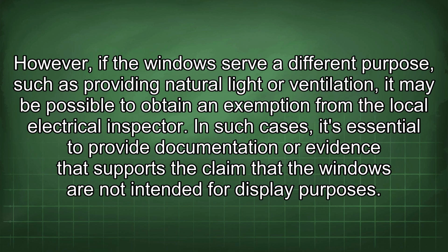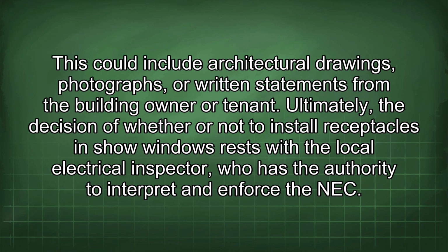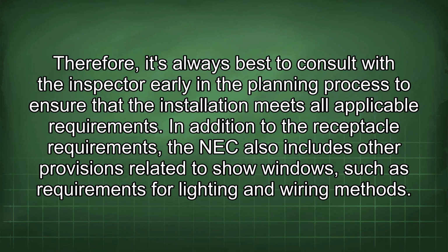In such cases, it's essential to provide documentation or evidence that supports the claim that the windows are not intended for display purposes. This could include architectural drawings, photographs, or written statements from the building owner or tenant. Ultimately, the decision of whether or not to install receptacles in show windows rests with the local electrical inspector, who has the authority to interpret and enforce the NEC. Therefore, it's always best to consult with the inspector early in the planning process to ensure that the installation meets all applicable requirements.